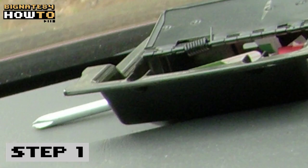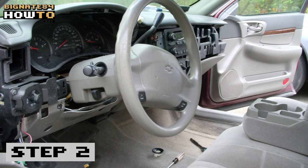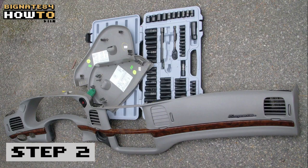Step 1. Remove the ashtray from the sliding compartment. It should just snap out. Step 2. Remove the dashboard. You'll need to locate and remove all the anchor points with the screwdriver and socket set. This is the most time-consuming part of the project.